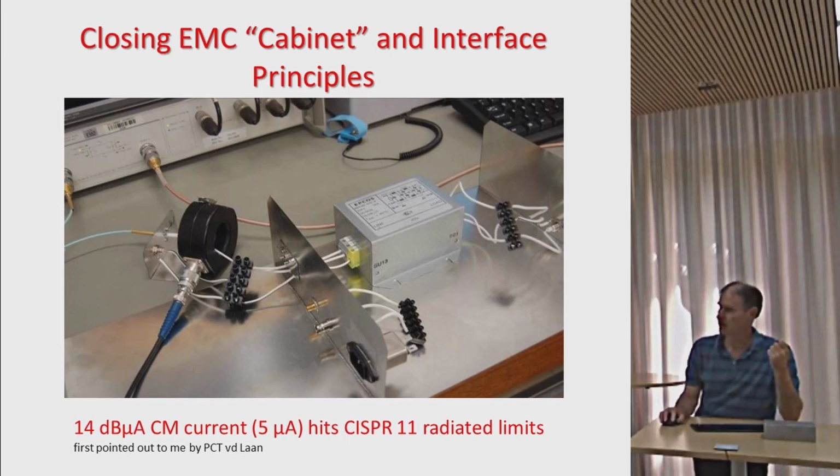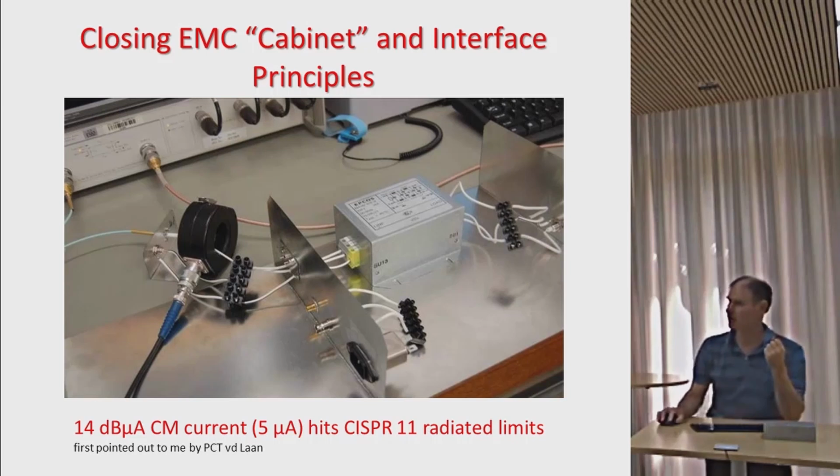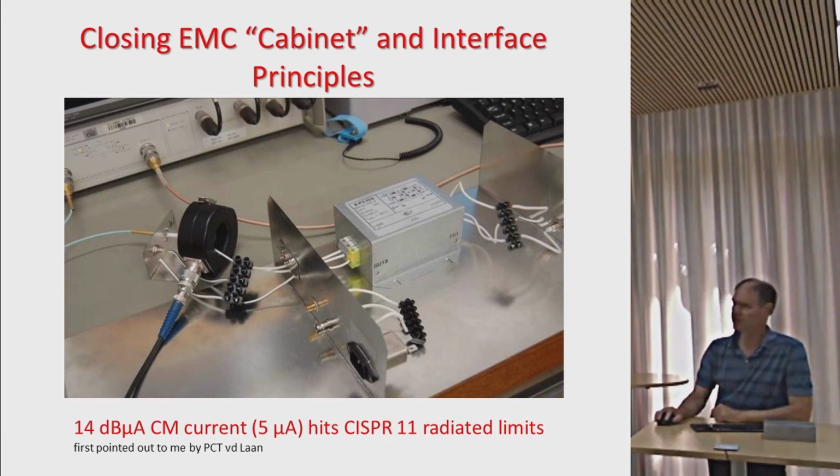What I do here is I use a current probe to measure the characteristics of the input signal. I either put in a capacitive barrier or I put a hole in the wall. And when I go through a capacitive barrier, the energy only goes through the capacitive barrier. Nothing from the outside world gets into the inside world except the current that I want. I properly ground the filter. The energy goes through the filter and the filter does a job of work.